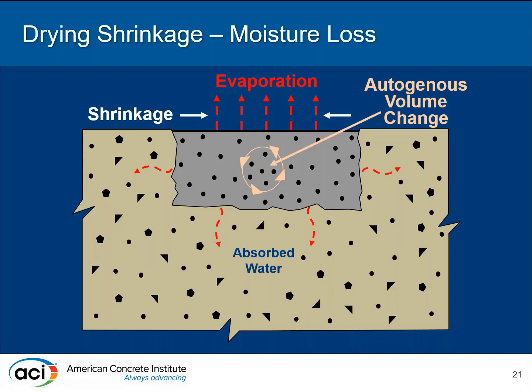That's one of those truisms that, if you're working in the concrete field, you should know. It's analogous to all concrete cracks. But frequently in a repair scenario, your original structure is decades old, hopefully, and has undergone basically all its shrinkage. When you're applying new material, fresh straight out of the box, it will still undergo a lot of shrinkage.